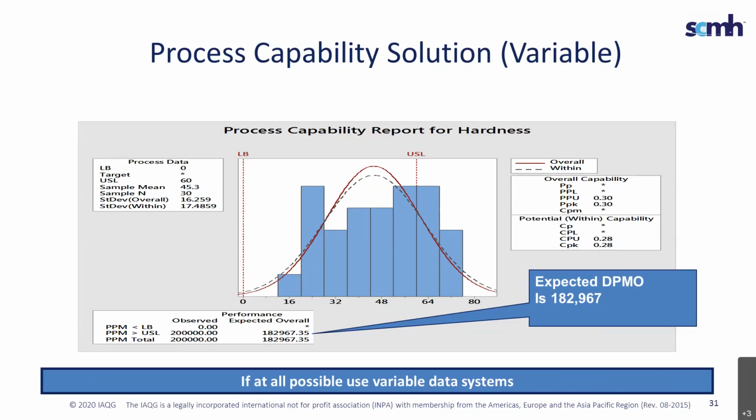But if you have a certain level of sampling, I would use that as your rational subgroup, and then you plot that. If it doesn't make sense, if you're only sampling 1 per lot of 10, then that is your rational subgroup. But you should be plotting them based off of your sample size and what you agreed upon with your customer. And you're going to have to always get 20 to 25 samples to start your CpK and your stability charts. So just keep that in mind.